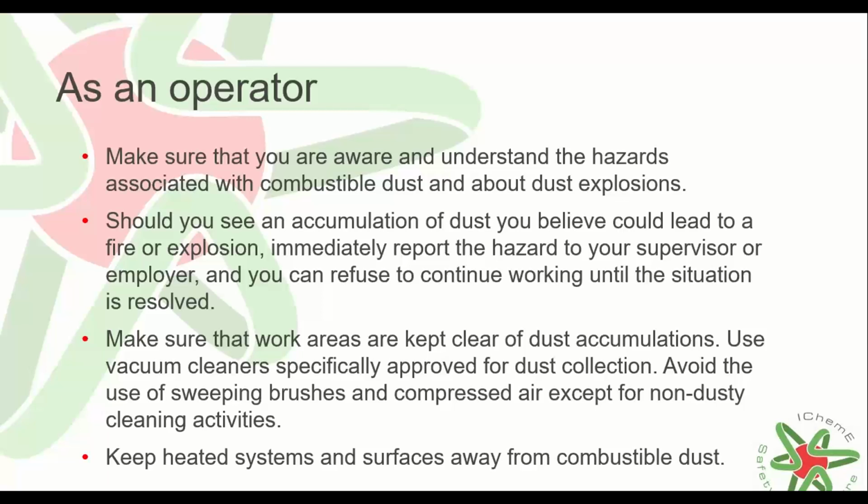Make sure that work areas are kept clear of dust accumulations, and use vacuum cleaners specifically approved for dust collection. Avoid the use of sweeping brushes and compressed air, except for non-dusty cleaning activities. Keep heated systems and surfaces away from combustible dust.